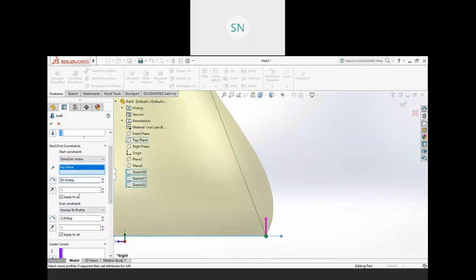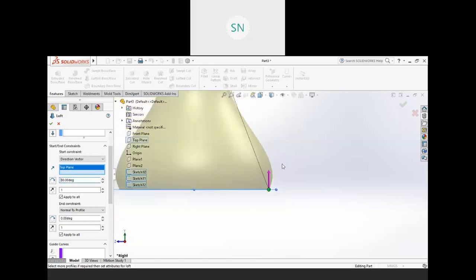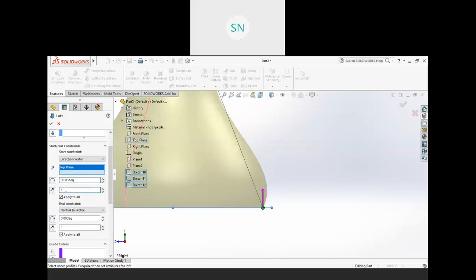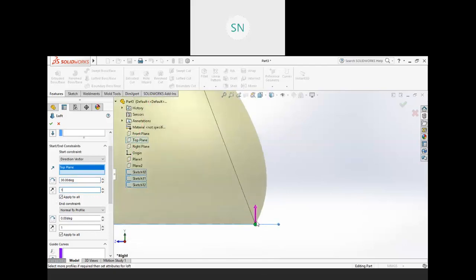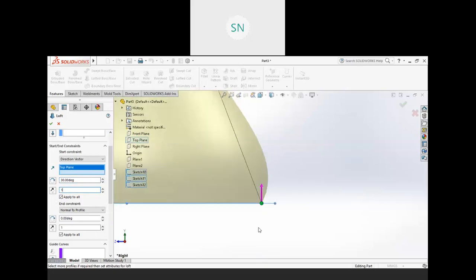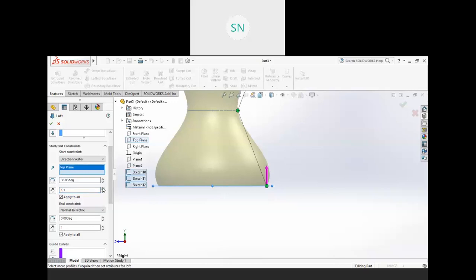So let's say 30 degree. So instead of this vertical, my curve is starting at a 30 degree angle like this, at this angle. My profile is going to start, right? And this thing is known as tangency effect. So if you increase your tangency effect, it will go up to the far distance. See, as I increase this, my effect will carry to some distance. So as you increase this angle, the tangency of that curve will increase.